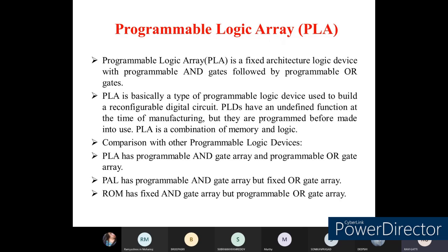So for all these cases, we need to check the output of the odd bit parity. For each bit, that is 0 0 0, there are no ones, therefore the output is equal to 0. In the case of 1 1 1, since it has an odd number of ones, the odd parity output will be 1.